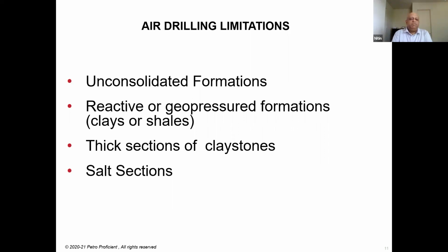If there are formations that require mud to maintain wellbore integrity, such as the one mentioned in point number 2, that is reactive shale or geopressured formations, those are the areas where you cannot use the air drilling technique or aerated mud technique or underbalanced drilling technique, because those formations will start to collapse. Again, claystones are formations where you cannot use it. You also cannot use air drilling where you have salt formations.